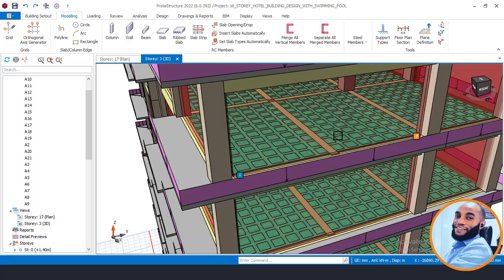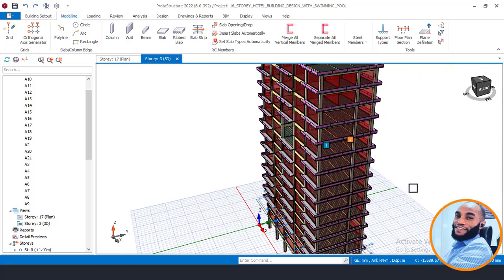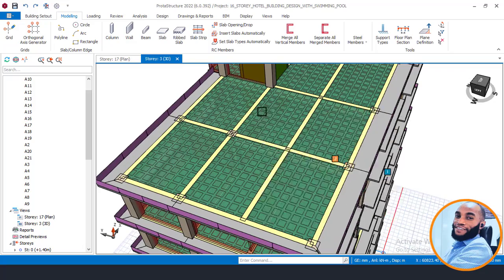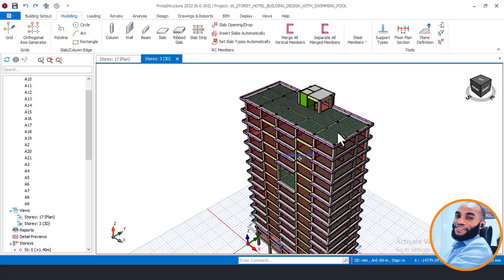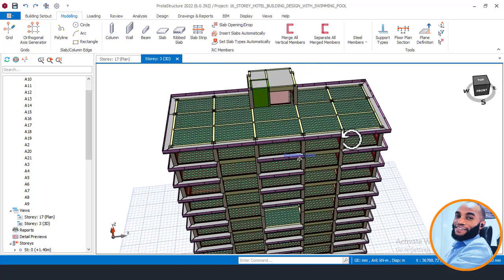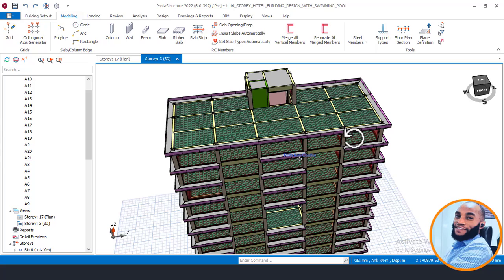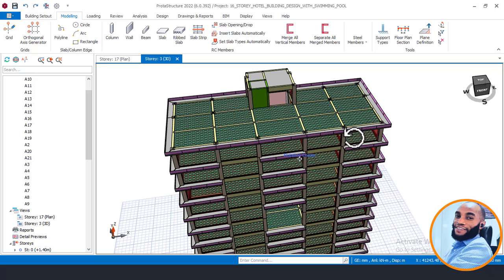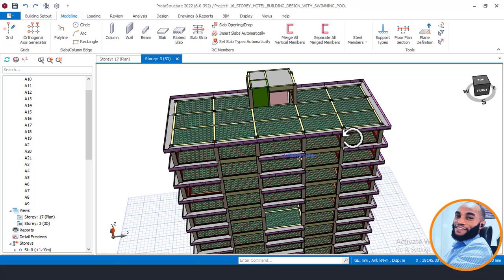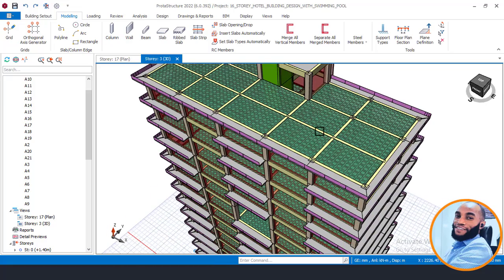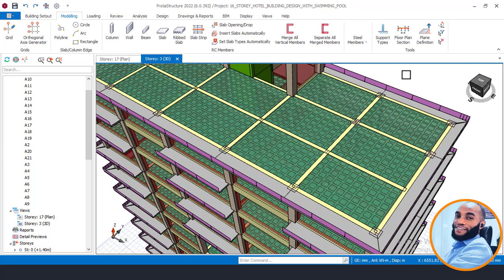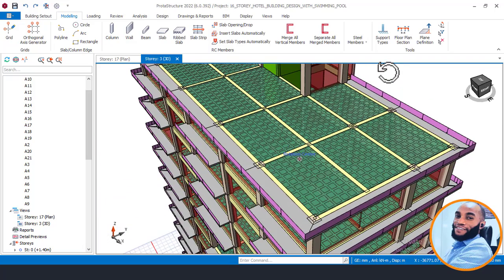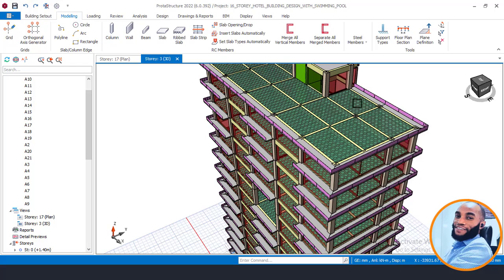Okay, so you can now see how the building is looking very light, because of this waffle slab that we have. It's looking light now compared to when it was just a solid slab. Okay, so on part 9, I'll be showing you how to reduce the load based on percentage, because we are going to apply those 2 methods of load reduction on this structure. The live load reduction method based on the type of the slab, which is changing from the solid slab to waffle slab, or what they call rib slab, and then also reducing the load again using percentage based on the story, which I'll show you on part 9. Okay, so watch out for the next.